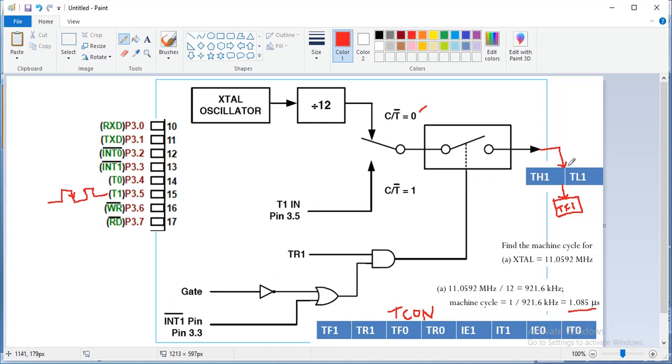So one car is inside the parking area. Again, one more car passes the proximity sensor and the next pulse is detected. It is received through this pin and counted. Now the register is incremented by one more, so the total count is 2.